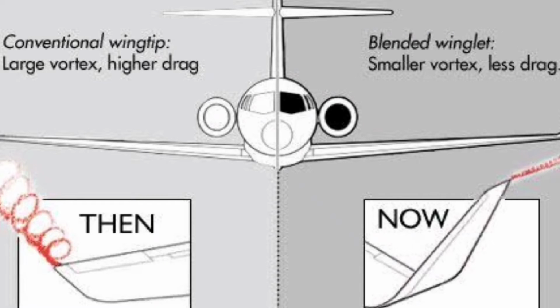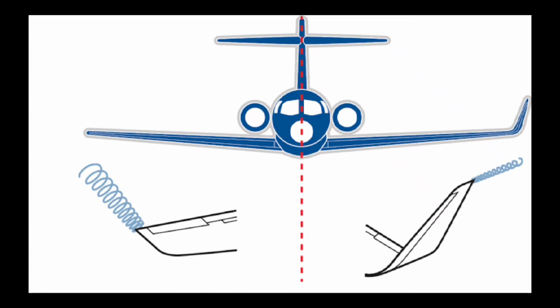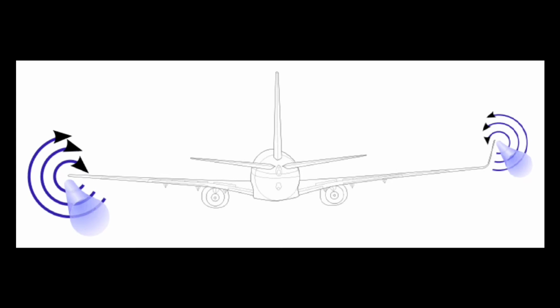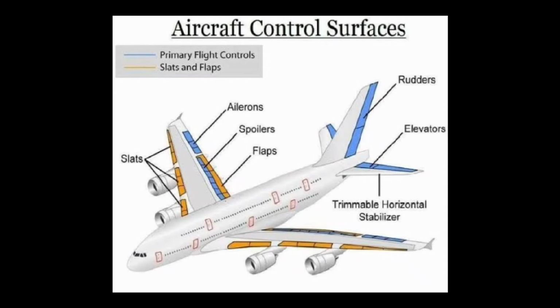The angle of attack should not be seen as a less important factor in lift generation than the airfoil shape of the wing. In fact, the AOA is the single most important factor. For example, a flat section wing can produce adequate amounts of lift all because of the angle of attack. The big difference is in the efficiency of the lift generation. Flat wing sections carry a large penalty in terms of much higher drag, compared to an airfoil section where drag is substantially less.